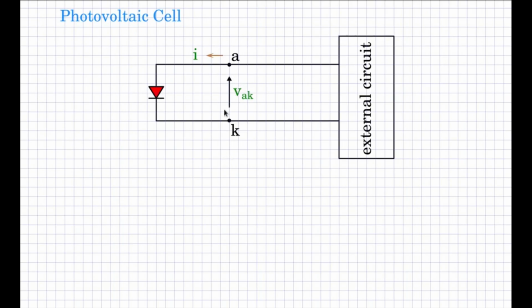So with this polarity of voltage VAK being taken as positive, that is the non-arrow end as the common point for probing and the arrow end as the positive terminal for probing for the voltage, and the direction of the current as shown here as positive, then we say that the power flows into the device, and the device is acting as a sink, and the power flow is into these one-port terminals.